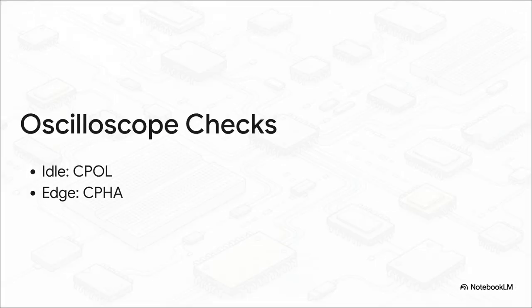But hey, what if you don't have the datasheet? Or what if your communication is just straight up failing and you don't know why? Well, you can actually reverse engineer the required mode using an oscilloscope. It's pretty cool. By looking at the physical waveforms, you just check the clock line in those quiet moments between data transmissions. If it's resting flat at 0 volts, boom, you know CPOL is 0.